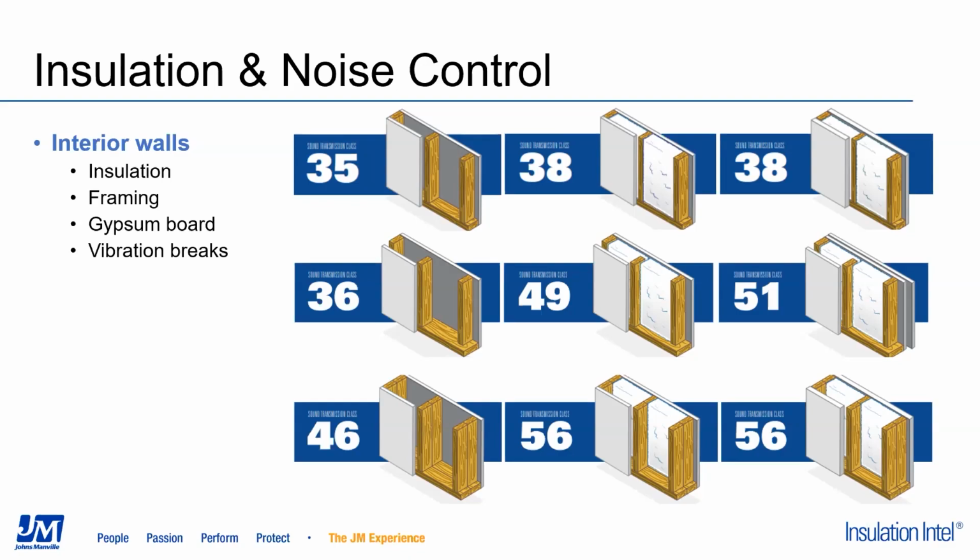And then finally, the bottom row, if you've got the space, it's ideal to go to a double stud assembly. You're seeing a lot better performance with this assembly because you don't have a shared top and bottom plate as you do with the staggered stud. You actually have a physical airspace between those two stud rows. So that's why we're getting a lot better performance, and that's helping us out quite a bit with that rating.